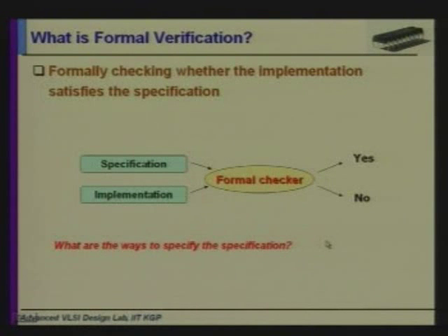Now as I said, that verification can be done through writing some test cases and properties and checking whether the properties are holding while running those test cases or not. It can be done in another way, in formal verification, where what we try to do is verify properties over all possible runs of the system, exhaustively. If there is any refutation of the property, we will get that if we do the formal verification.